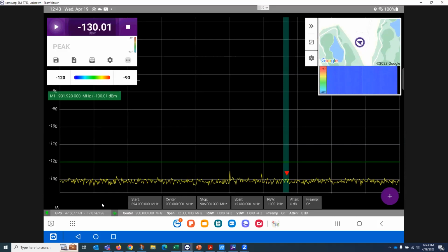As Eduardo talked about, the system is designed to look at a massive amount of spectrum for us, the end user, but when it's trying to make its calculations to help you isolate and geolocate an interferer, we're going to isolate that down to a given area. Some people call them PRBs. I do, right? It's the uplink slots that I get to play with, right?